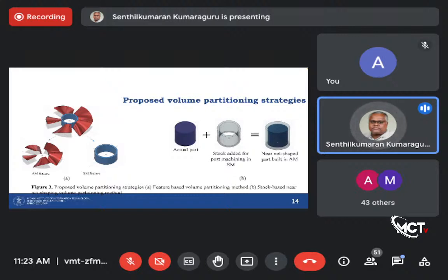So it's really challenging, holding the workpiece and maintaining the datum, dimensions and geometric tolerances for the mating condition, because they are all going to be assembled onto a shaft. So the moment somebody throws a part like this at you, additive manufacturing can make these blades very easily. You can slice them and make them very easily. For AM it's very simple. For machining, it could be really complex.